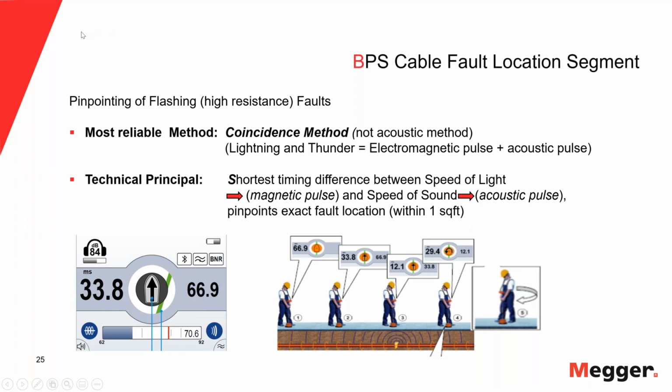And because, like Marshall was saying, typically I have to cut the cable, and I don't want to cut the wrong cable segment. So it's always good if you have a chance to verify a pre-location result with a pinpointing result. It's a very good practice, regardless whether in conduit or not in conduit or direct buried.